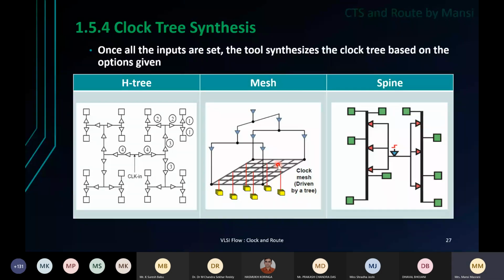Okay, but there is one drawback over here. This is also very finely balanced for skew and it's very good for timing, but there is some issue over here which we will talk about. Now there comes a spine. This is not really balanced for skew, because if you see over here, the clock came to the center, then it divided into a comb-like structure, all these red buffers.